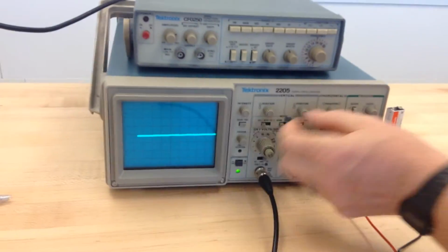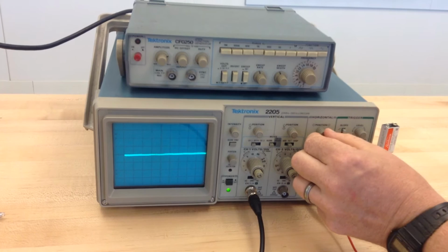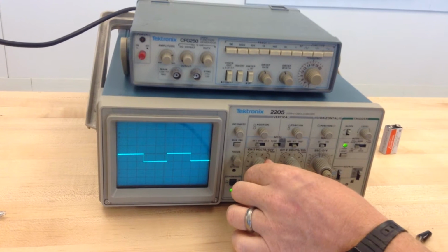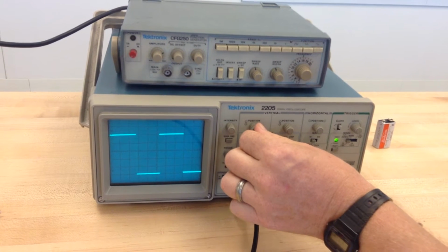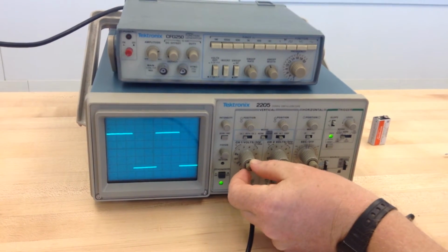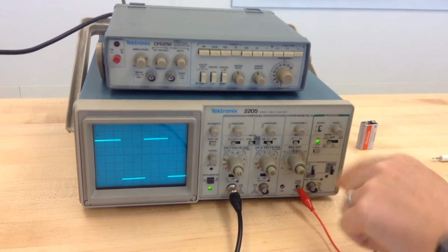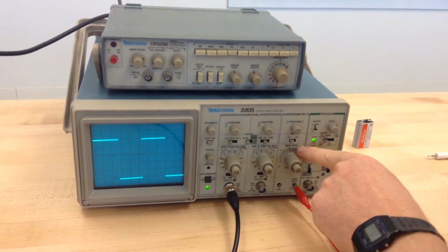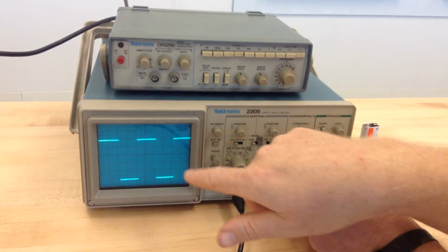Okay, so I'm going to adjust a position where it's convenient for me. I'll move it over. Now I'm going to increase it. 500 millivolts peak to peak means that's half a volt. So if I put in 0.1 volts per division, my signal should be 5 divisions high. And let's see, I can calibrate this so that I have my signal 5 divisions high. And there, that's good. Now, it's 1 kilohertz, that means a 1,000th of a second is how long it takes to start its cycle again. And so at 0.2 milliseconds per division, I should be 5 divisions wide.